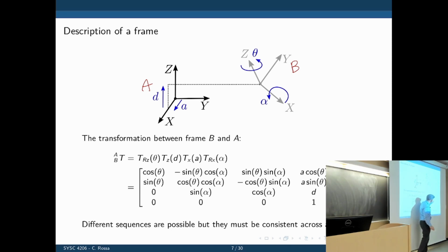A, the shift translation across X. So if you want to find the entire transformation matrix, all we need to know is the translations and the rotations, and then plug the values here and define the transformation that way. The good thing about this is that we now have a convention that works for all joints in a robot arm, so long as we are able to properly position these joints in different strategic points in space.